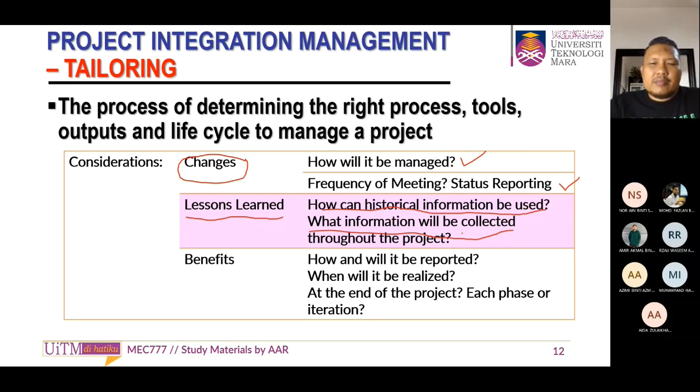When I check, I ask them to give me the room data sheet, then I can check, for example, the fire extinguishers: is it enough or not? What you promised, for this huge hall, is it only one fire extinguisher? Because you have 2 exits, for example, 2 entrances. So is it enough? I need to check the room data sheet. Based on the Bomba requirements, is it enough? Yes, enough. But based on normal practice, this is not good practice. So that's why we need to check, and start from that. That is a good lesson for me. I used that lesson learned for the following projects.